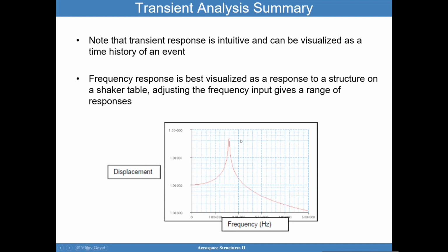And so here is what we had discussed earlier: as I vary the forcing frequency and get close to the natural frequency, you'll get a peak response. And as I move away, I have less of a response. And so this becomes very important in the design of structures.